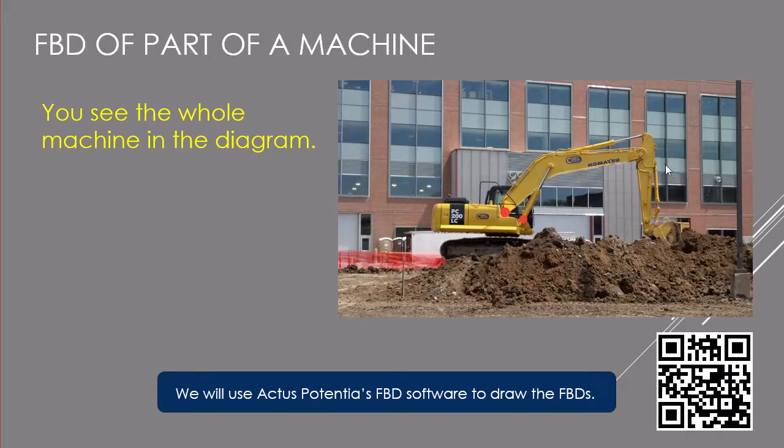the whole machine is here. We take this pin off and this pin off and separate the front part of the body. But we will have to include the effect of these two pins. So there will be two forces here and only one force here. One force here because the hydraulic cylinder is a two-force member.